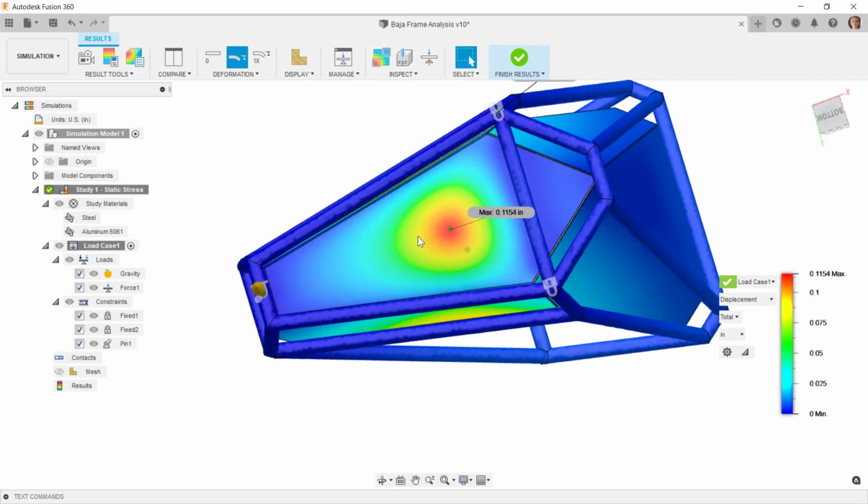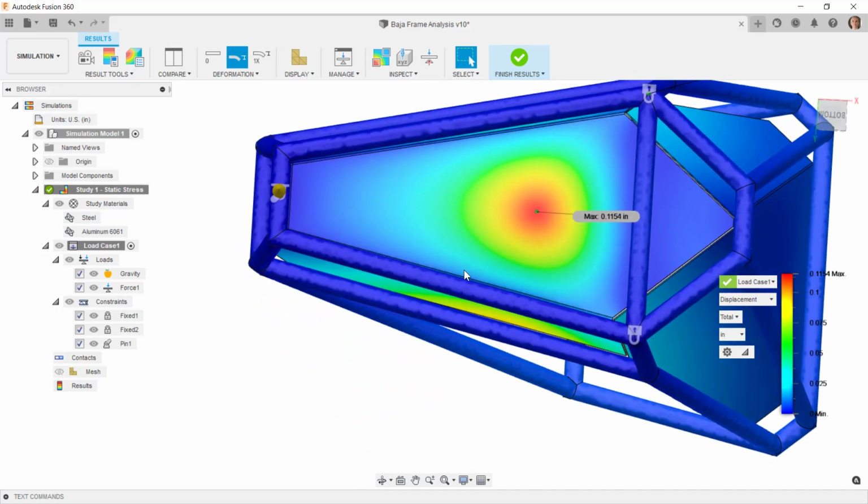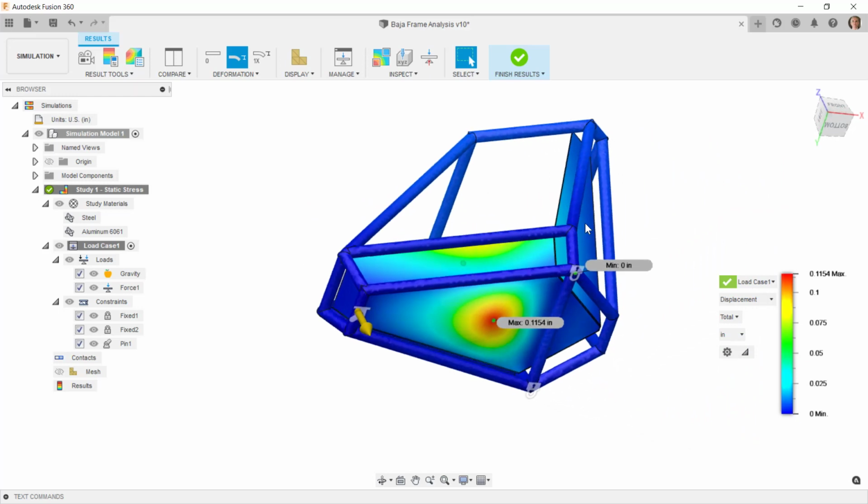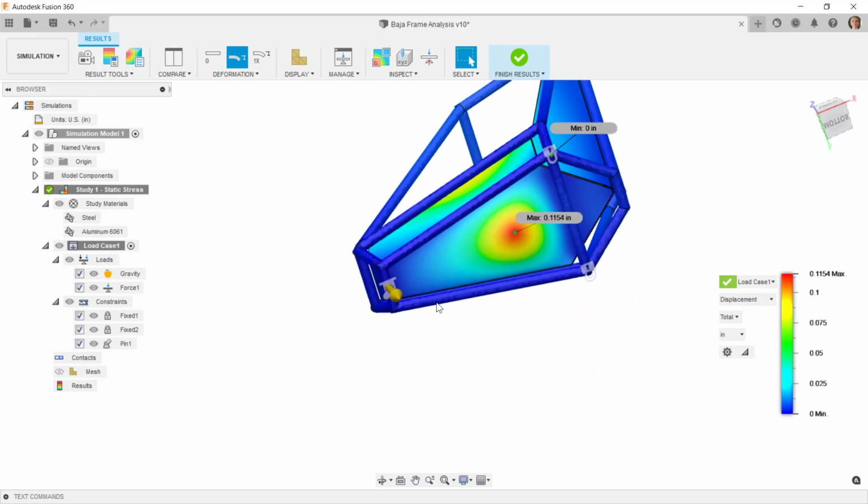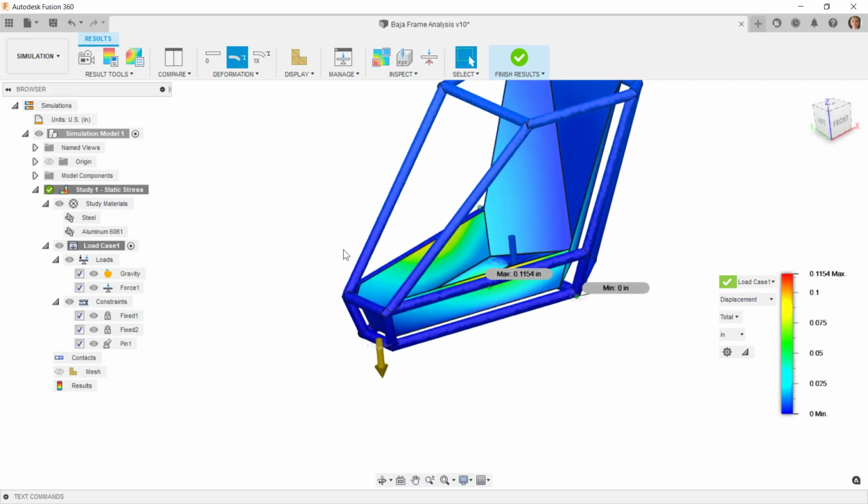And so we may want to, in fact I'm pretty sure you'd want to put another beam element across here, and so the seat that the person is sitting on would be bolted to the beam here and to here. And then you may want one up here too where they would put their feet in the pedals of the steering column, because all of that would put more of a load up here as well.